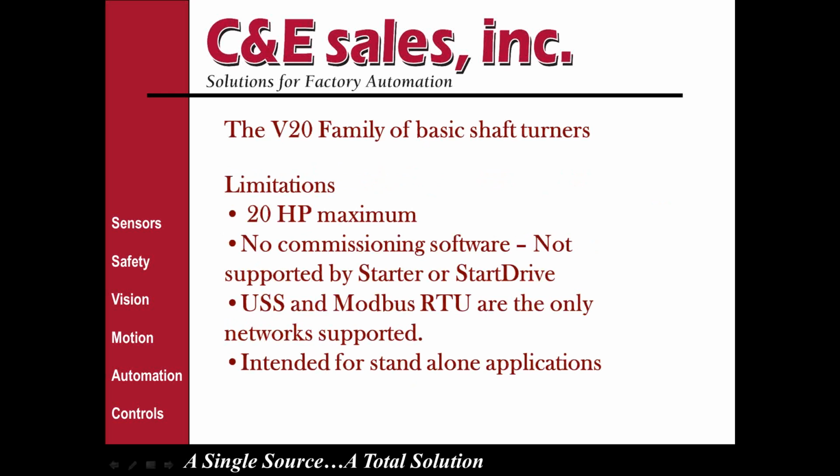Limitations on the drive: 20 horsepower maximum is the max this V20 family goes. And unlike all the other drives available from Siemens, there is no commissioning software available for the drives, and none that has been announced for the future. So this is not supported by Starter or Start Drive, which are the commissioning packages used on all the other drives that we'll talk about today.